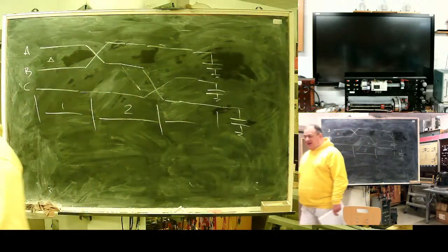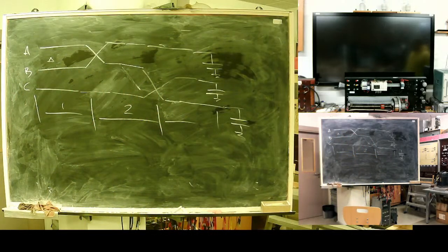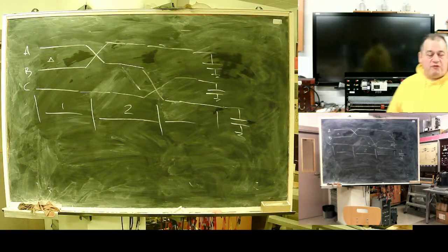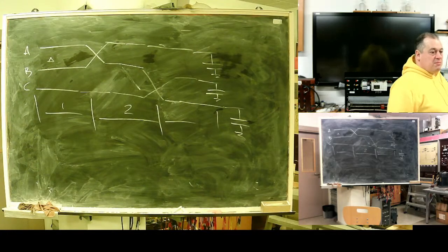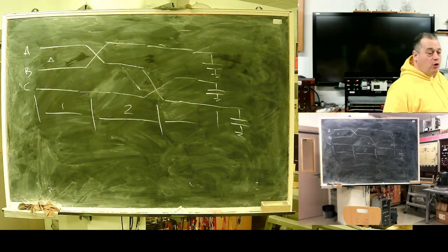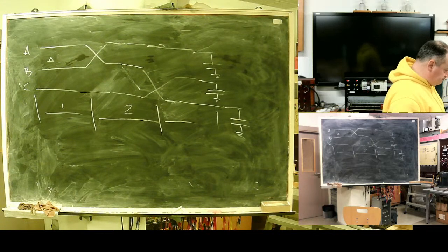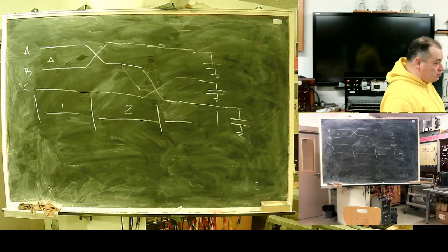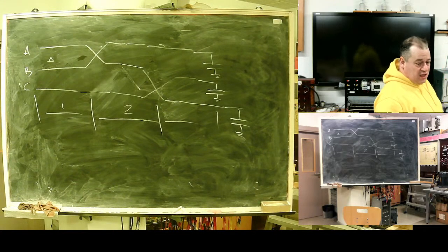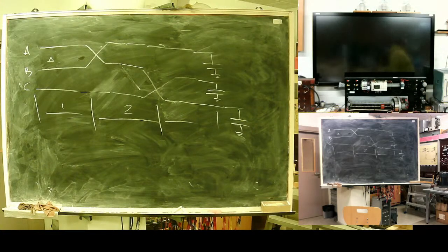For 110, it's a rare thing. For 330 and above, it's mandatory, because asymmetry in capacitance at high voltage produces terrible equalizing current and huge losses. So it's absolutely normal practice to design lines with transposition at high voltages.